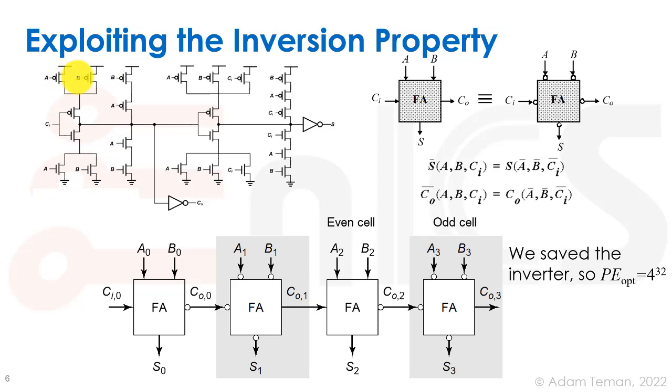We have these two PMOSs in parallel connected to a PMOS in serial, and the same thing we can have for our pull-down network with NMOSs, and the same over here, and the same over here. And that is not standard CMOS. Usually we have a NOR network on one side and an AND network on the other side, or something like that. But here it actually happens with this full adder, and the benefit is that we pull out the carry computation really early, and then we can get the sum, which is not on our critical path, a bit later.